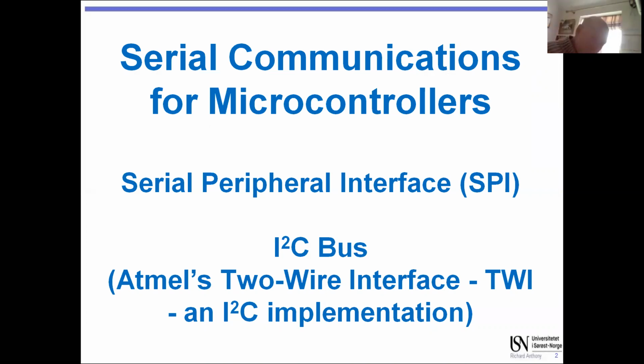So the Atmel has got not just the COM ports, it's got the serial peripheral interface, and it's got this thing called I2C, which is actually in Atmel's implementation, and in the manual they call it TWI. That's because of a complicated legal situation many years ago where they weren't allowed to call it I2C, but it is fully compatible with I2C, which is an industry standard, by the way. So it's important that it does work with that. And I know from personal experience, it works perfectly well with I2C devices.